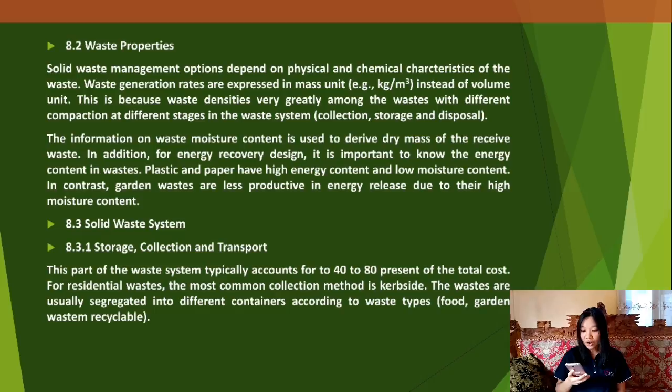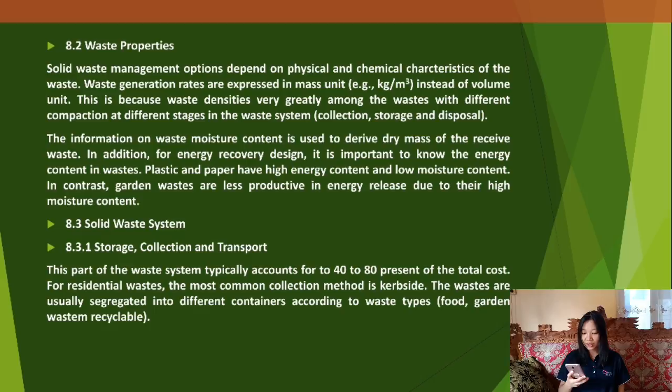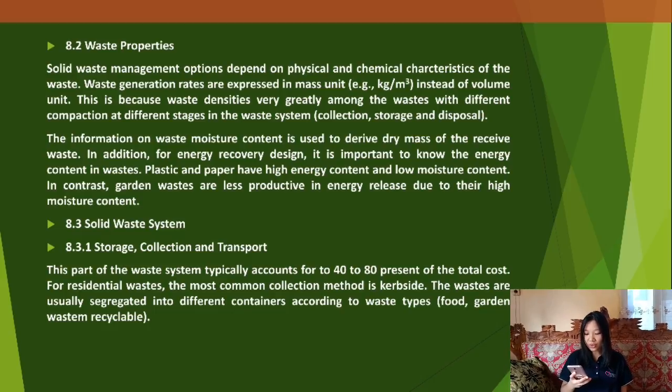In addition, for energy recovery design, it is important to know the energy content in waste. Plastic and paper have high energy content and low moisture content. In contrast, garden waste is less productive in energy release due to its high moisture content.